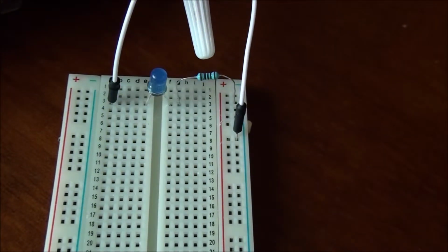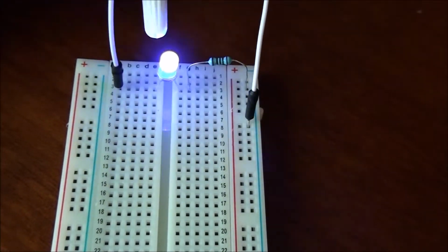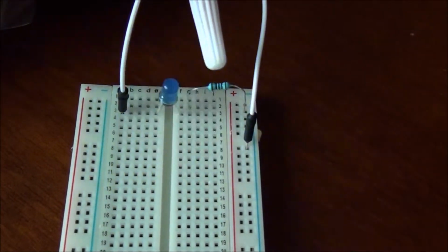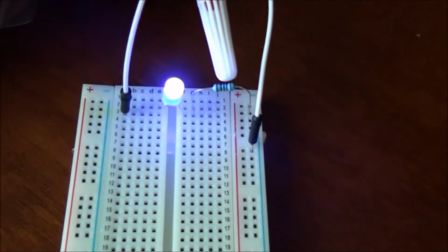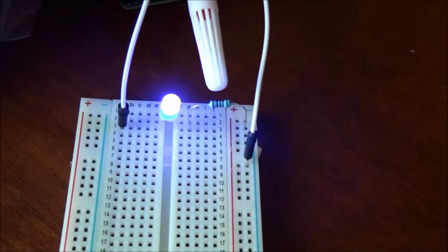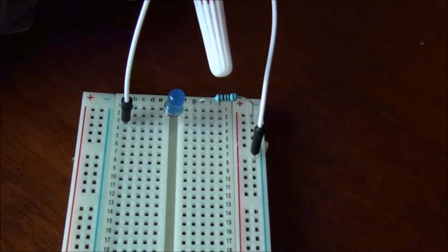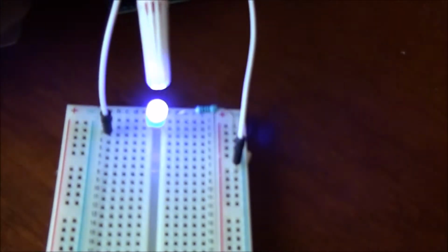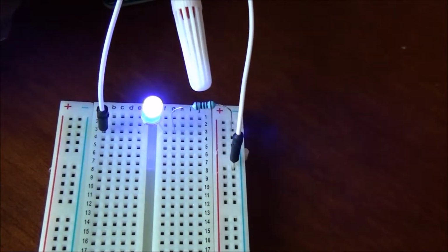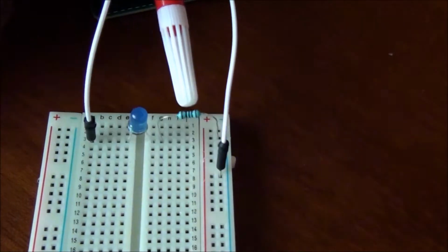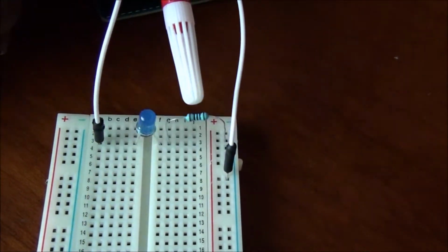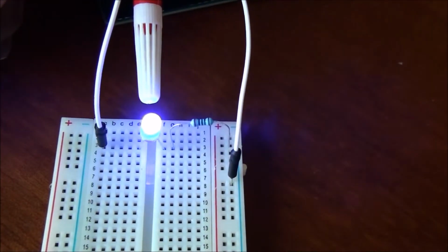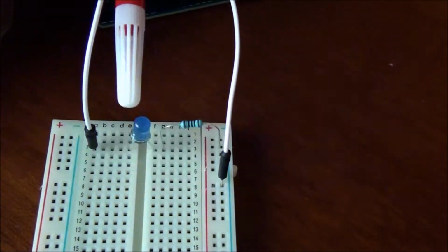Now for this exercise, with this blue LED, we're going to use a 100 ohm resistor. If you don't quite have a 100 ohm resistor, don't despair. If you have a resistor with a higher resistance, like 200 ohms or whatever, it means you're reducing the current to the light, which means it's going to be dimmer. Not a big deal. If you have a resistance which is less than 100 ohms, it means you can have more current flowing to your LED, which means it's going to be brighter, which may seem like a good idea, but you are also reducing the life of the LED lamp.